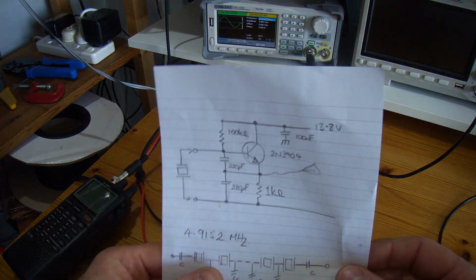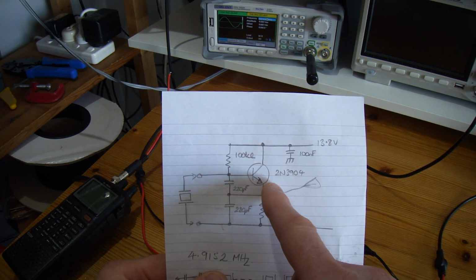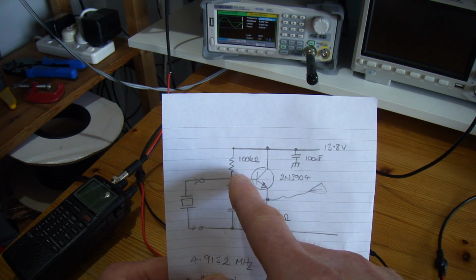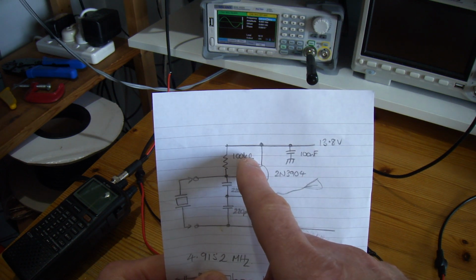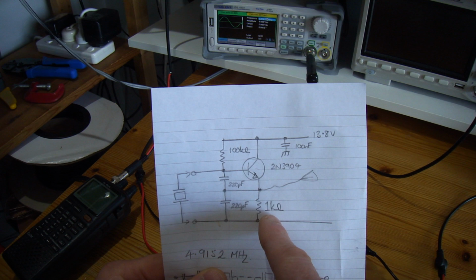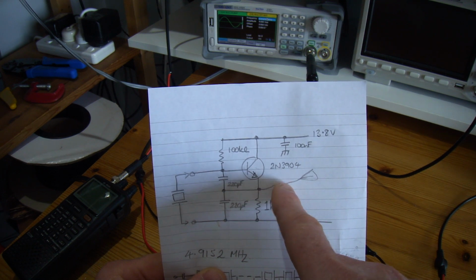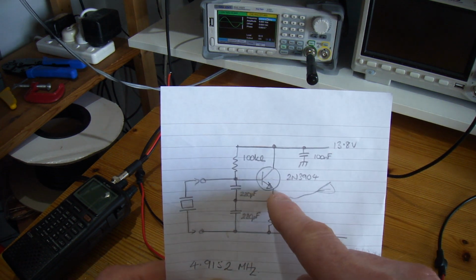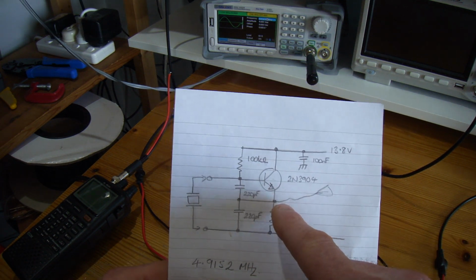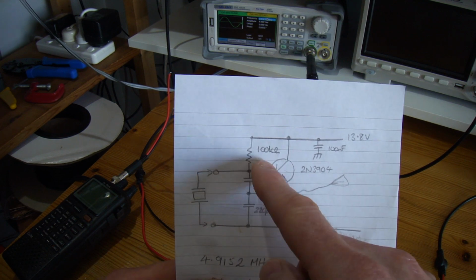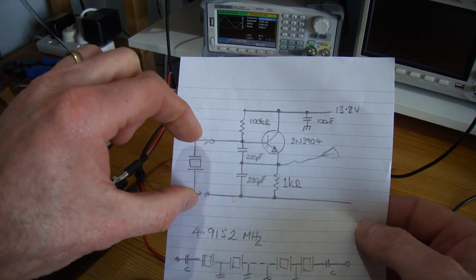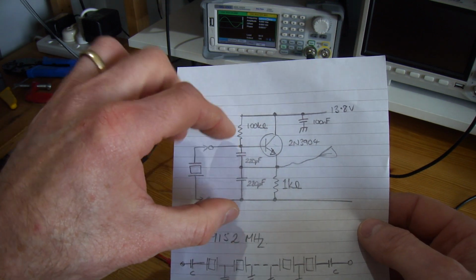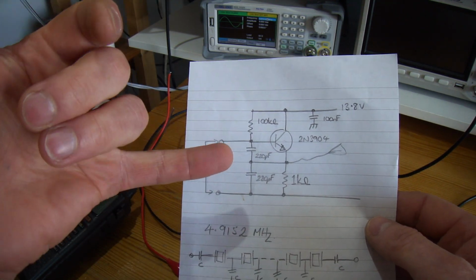The actual crystal oscillator is very straightforward. Again, just a 3904. Fixed voltage biasing here off the 13.8 volts of 100 k ohms. In the emitter, I just throw a 1 k ohm there with a small fly lead that you can see there. You don't actually need it. There's enough RF being emanated or being radiated, more the point, for the radio. And then on the input side, just the split capacitors with the crystal under test across that, driving the overall frequency, and that works really well.